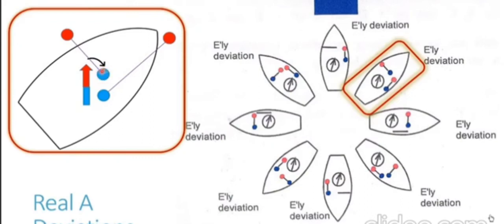Now one doubt may arise that since there are two blue poles now, the deviation generated will be more powerful, but that is not the case. Reason being, even though two poles are generated, both of them have partial power. Why is the power partial? Why is their strength partial? Because they are not perfectly aligned with the magnetic field of the Earth. Both the longitudinal and the athwartship beam are partially aligned, making these poles partially powerful.